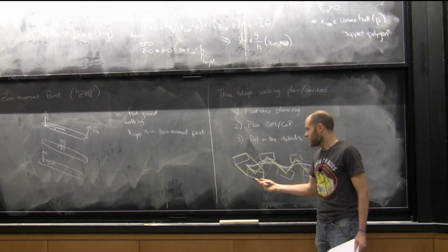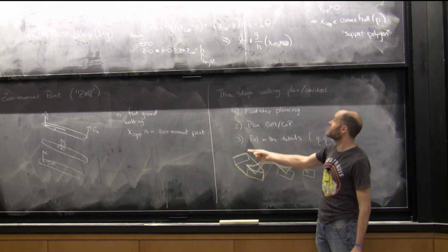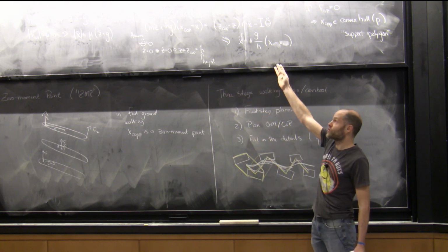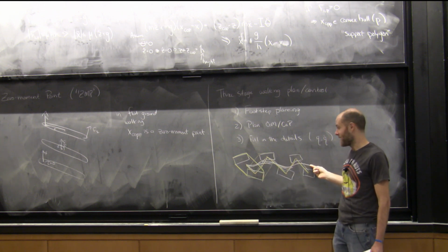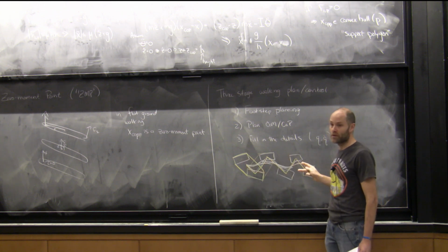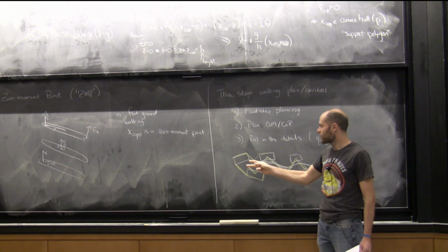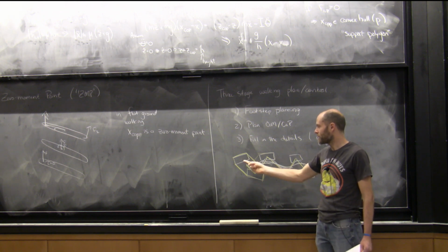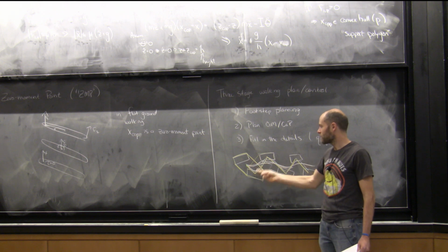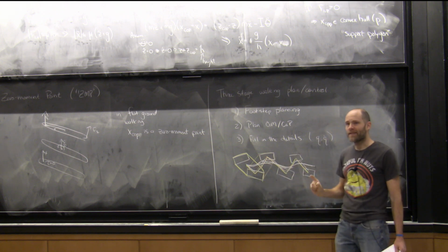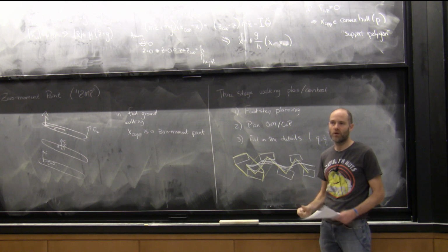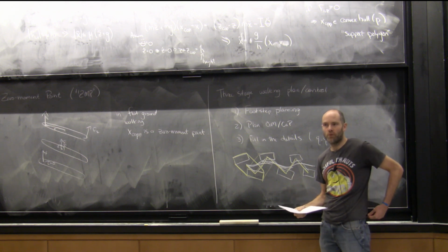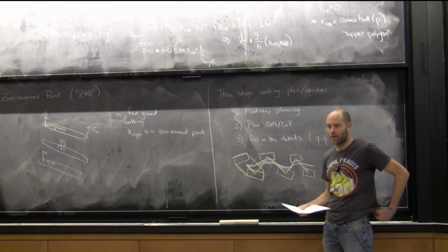Similarly, I mean, it's a particularly easy one. It's just an unconstrained one. So you can actually write down the LQR solution to this and stabilize your center of mass given the footstep schedule and the timing. Even when I tell you about footstep planning, the location of the footsteps is actually fairly easy. The timing of the footsteps is gross. I think we still don't have great solutions for when to put your foot in different places.